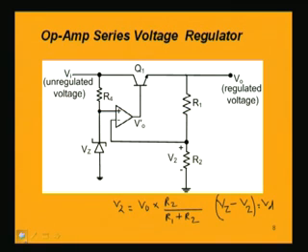So what happens is that V0 dash will be now decreasing, and V0 dash and V0 are almost equal. This is basically an emitter follower, and the output voltage V0 is almost equal to V0 dash, because V0 dash minus VBE is this voltage V0, but VBE is very small, so we can almost say that V0 dash equal to V0. That means now V0 will be also decreased.